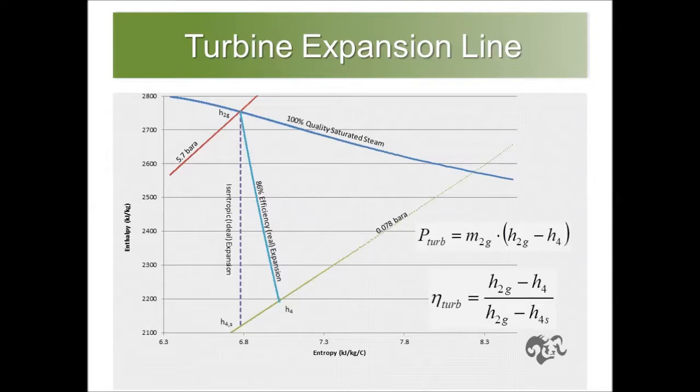There are also pressure and velocity losses at the turbine exhaust. The turbine's exhaust steam has a large specific volume and is traveling at high velocity, resulting in frictional losses in the ducting between the last turbine stage and the condenser. Also, the velocity and energy exiting the last stage blades is lost. So the used energy endpoint at the outlet of the last stage blades is somewhat above this H4 point.